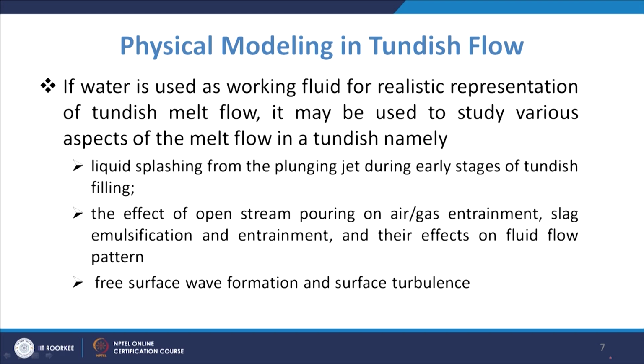Effect of open stream pouring on air or gas entrainment, slag emulsification and entrainment, and their effects on fluid flow pattern. This is another area on which you can have the physical model preparation. Similarly, on the free surface of the tundish you can have wave formation. These can be studied, and even there is surface turbulence. They can be seen using the physical models.